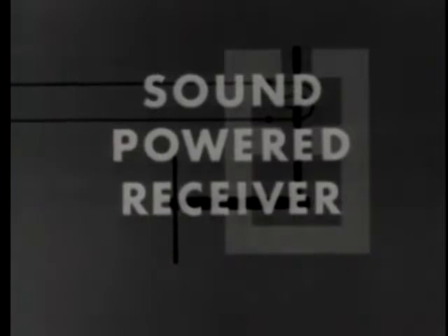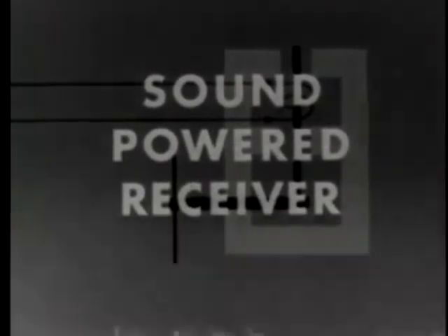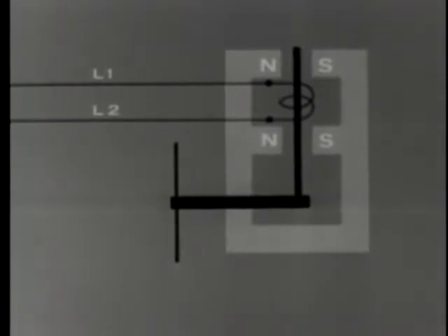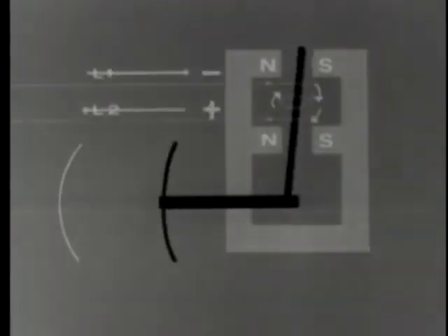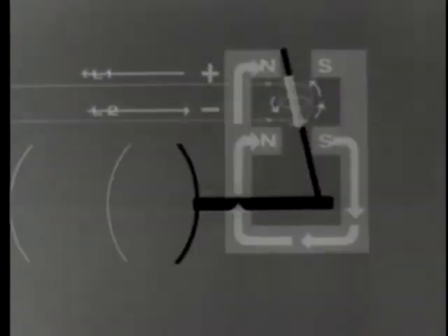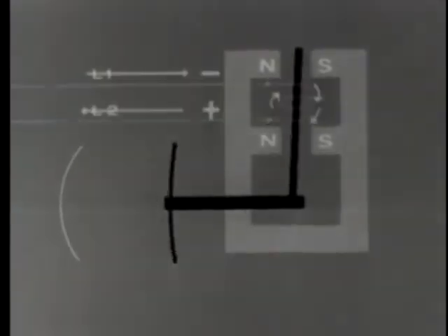At the other end of the line, a device similar to the transmitter reconverts the electrical current into audible sound. The telephone receiver, however, employs the principle of electromagnetic attraction and repulsion used in the operation of the ringer. As the voice current in the coil alternates, the polarity of the armature reverses, causing each end to be alternately attracted or repelled by the permanent field magnet.